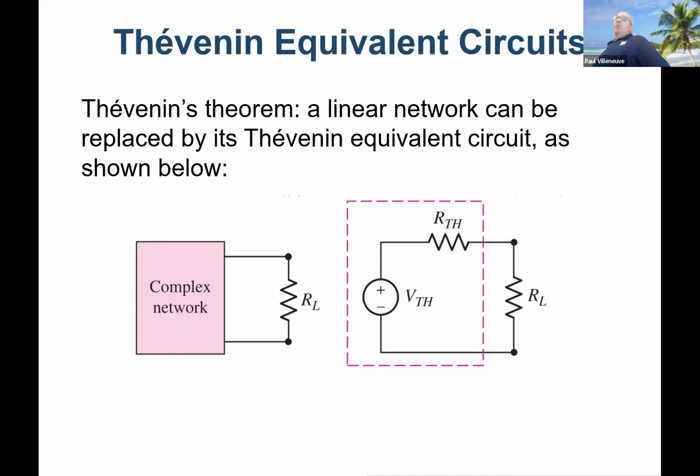In the real world, do you do a lot of Thevenin and Norton? Absolutely. One of the things, if you take a class from me called Power Systems Analysis, we actually determine what the fault current can be at any specific location just by knowing the pre-fault voltage and the Thevenin equivalent. So I can model the really big, complicated utility system with millions and millions of pieces of equipment, and I can tell you what the fault current is going to be at a specific location. So that's why we do a lot of this stuff here.